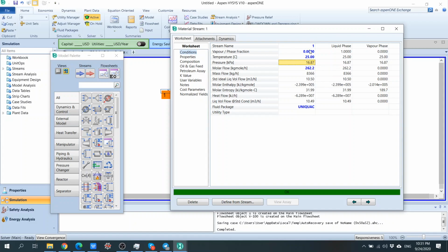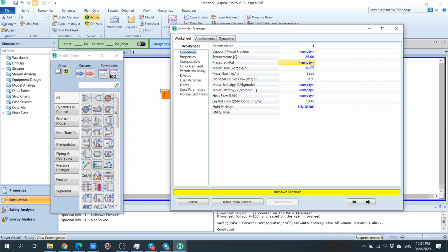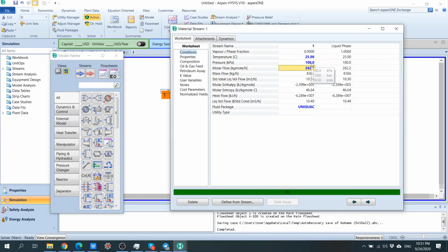So if it cannot be vacuum, and it cannot be like 65 degrees C, and it's not saturated liquid or saturated vapor, then it has to be subcooled or superheated vapor. It cannot be superheated vapor because it's a liquid, right? So it has to be subcooled. So now you know that this guy I cannot specify, so I need to specify the temperature and the pressure. Hence I get this. This number fits the data, this number also fits the data, and then you can be happy. So I will see you again next week.